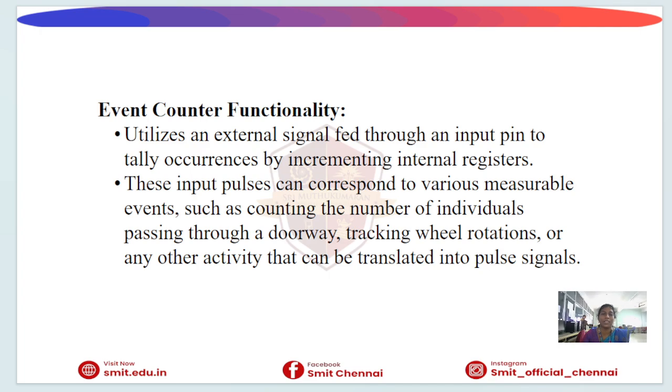The next one is the event counter functionality. This is the counter mode. The timer does not use the internal clock. Instead, it counts the pulses applied externally. Real-life examples are counting the people entering a hall, counting the students in a classroom, and counting the products on a conveyor belt.